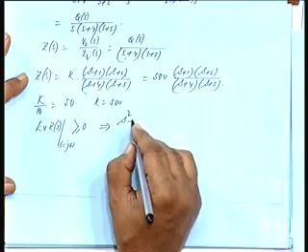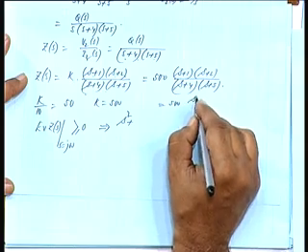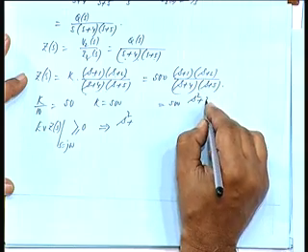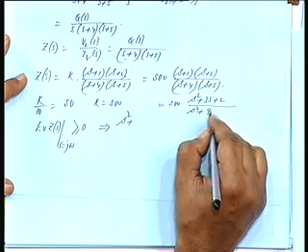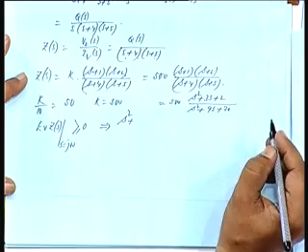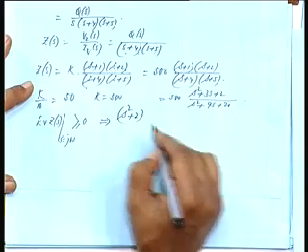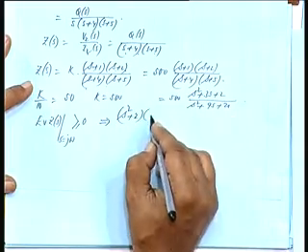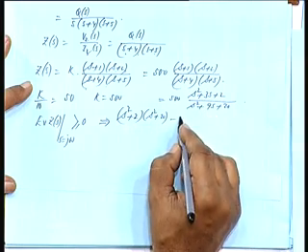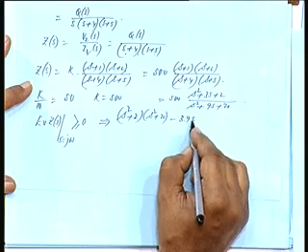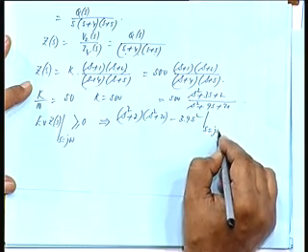I can write this as 500 into (s squared plus 3s plus 2) divided by (s squared plus 9s plus 20), is it not? So, even part is (s squared plus 2) into the even part of the denominator, s squared plus 20, minus 3 into 9 s squared, to be evaluated at s equal to j omega.